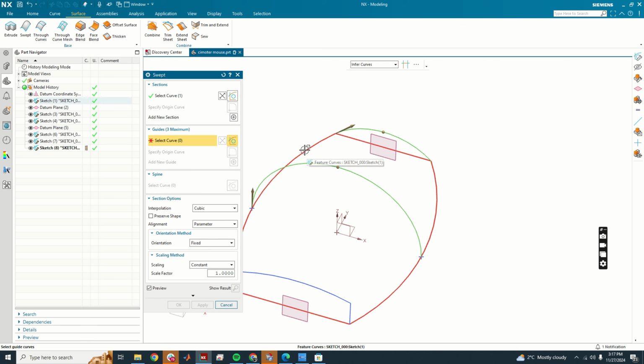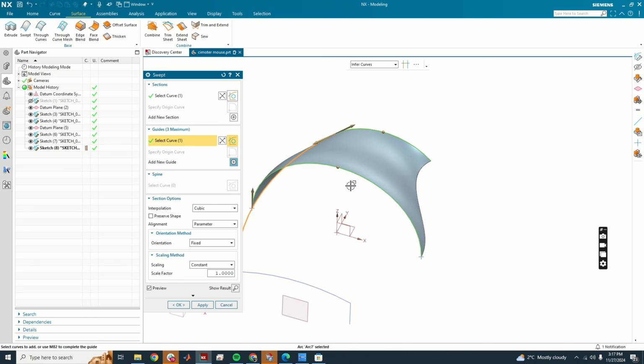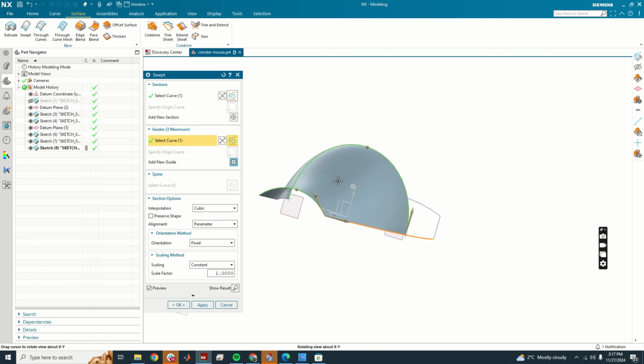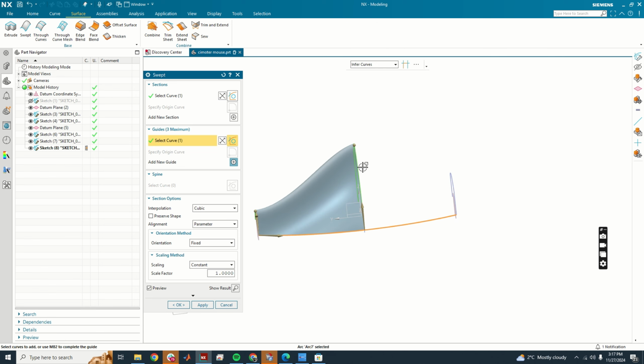And see how I hover over this and it is highlighting this entire big sketch? That's because it's still visible and it's just not letting me select the one underneath. So I'm going to go over here and click on this little eyeball, and that's going to hide the big sketch. Now when I click on this, I know I'm selecting this last one over here. So I select that. Hey, there we go. We just needed a guide curve. Okay, good to know. So that is creating a cool little geometry between one curve and another.